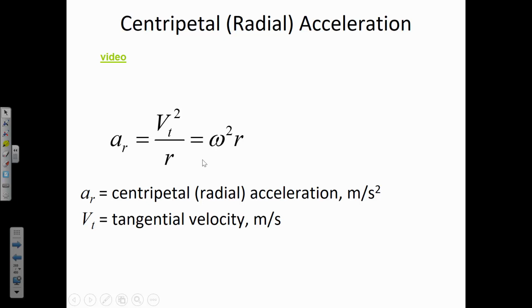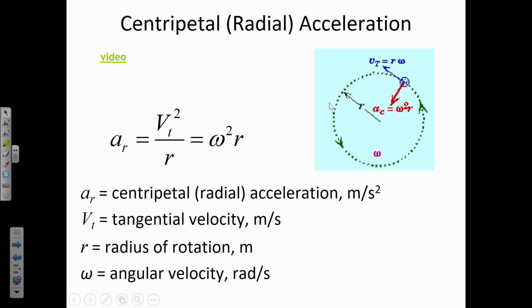The tangential velocity would be the speed of some particle. If we multiply the radius by omega, the angular velocity, then it's actually the magnitude of its velocity, its speed. Of course, its direction is always changing. Sometimes there are questions about the actual speed of a fan blade at the outside edge of the tip as it's rotating. The way that you'd calculate that tangential velocity is you multiply the radius by the rotation rate,